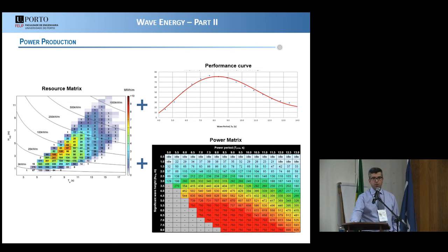I think it's not a simple topic because since the waves are very irregular, the motions of the devices are also very irregular, and also the output from the power takeoff system. And that is not good for the grid. So we want to have a smooth power curve. One thing that we are planning to do in the near future is to use supercapacitors to absorb the peaks, but that is an option for the experimental tests that we intend to do in the near future.